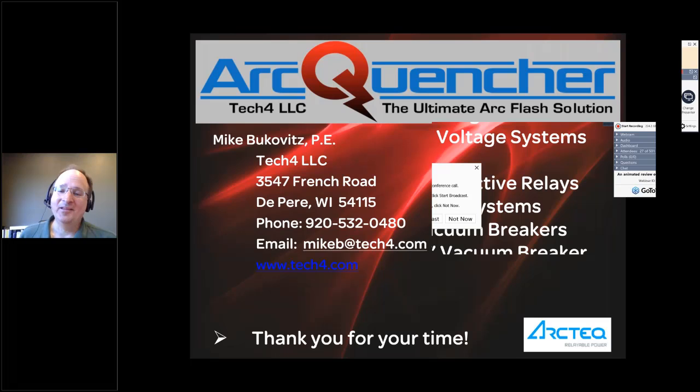That's a great question. In the same way, as everyone's probably aware, we really don't have an IEEE 1584 equivalent for DC, right? We know DC causes arc flash. That's how an arc welder works. But the models we have for DC arc flash are strictly, at this point, theoretical. We're just waiting for an enterprising power system engineer and someone with a lot of money to develop an IEEE 1584 for DC. The same applies to arc quenchers too. So, great question, but at this point, the quenching is always done on the alternating current side of the inverter.